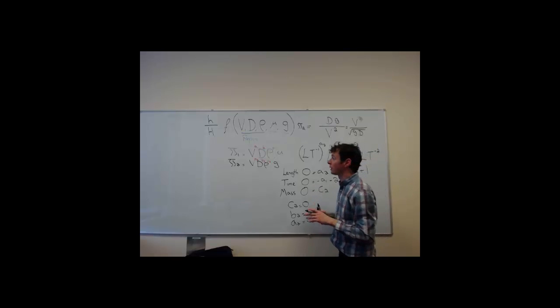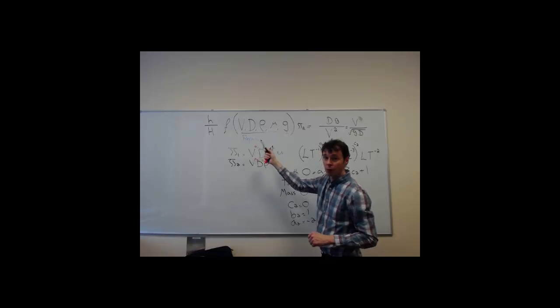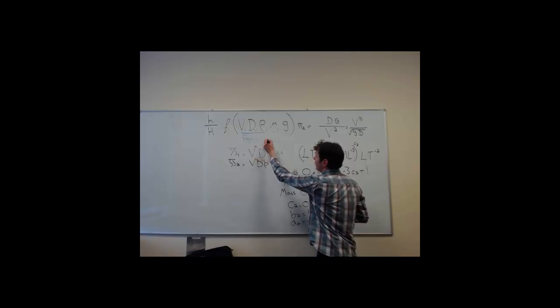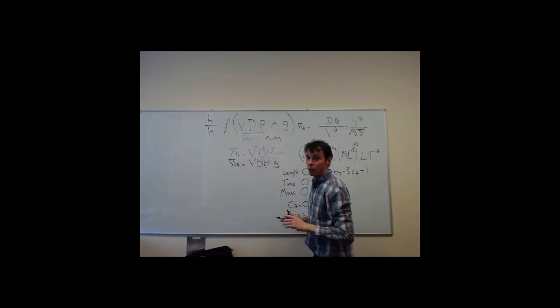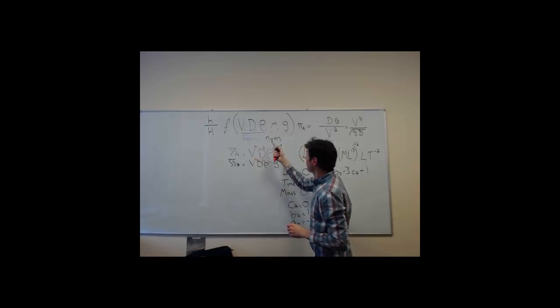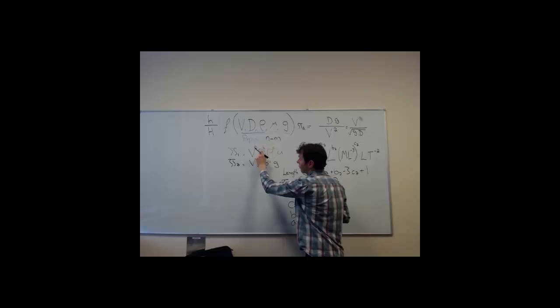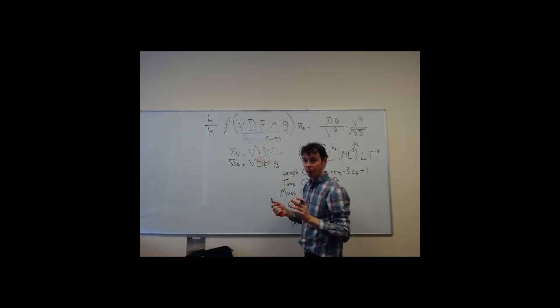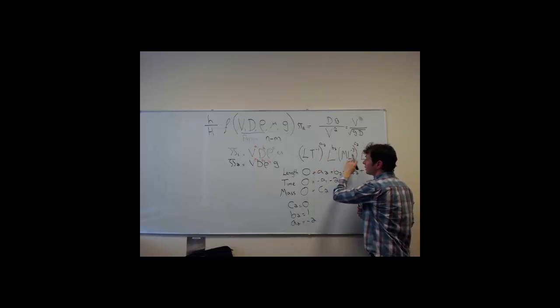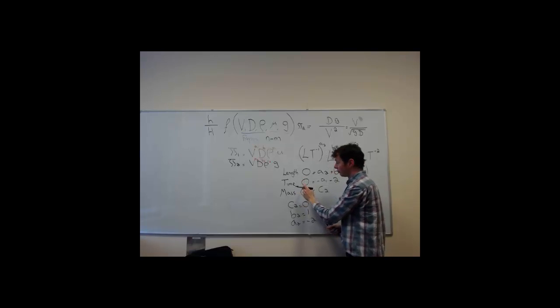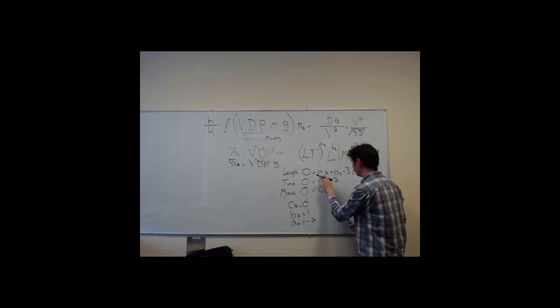So just follow the steps very carefully. Write out all of the parameters that are important in the problem. Write out their fundamental dimensions, and then use the n minus m approach. So you know how many groups you're arranging them into, and then for those groups, assign one variable that will only appear in one of the pi groups, and then the others will appear in all of them. Okay, and then we raise all of the repeating variables to an imaginary power, and then we write it out in this longer form, and then you equate each of the dimensions in the problem to 0. Just take care of this step.